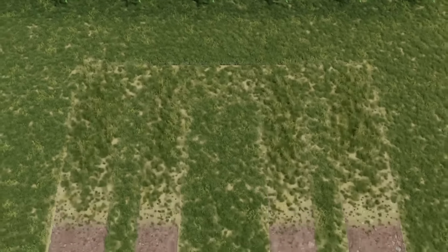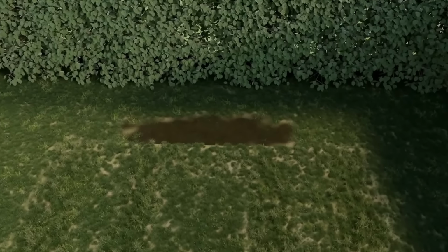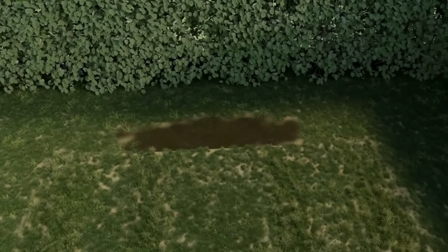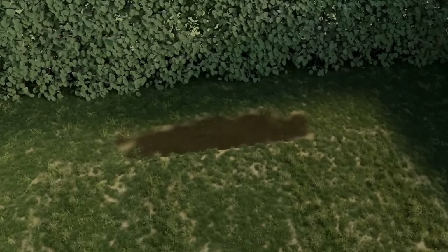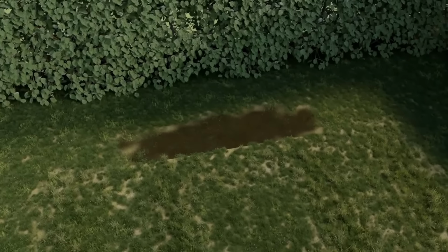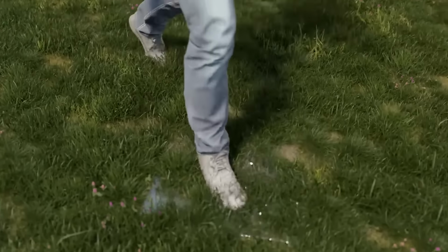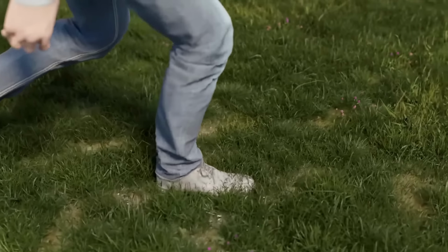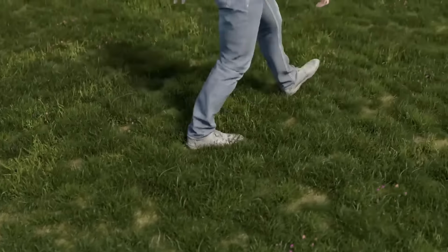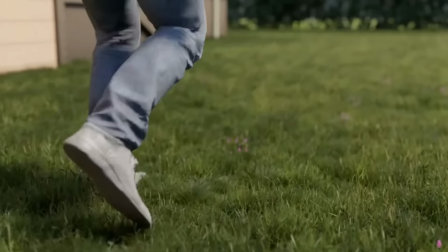If you notice taller, greener grass where your leach field is located, it is an indicator that your leach field is not functioning properly. If you notice puddles on the field, it is possible that a hydraulic overload has caused the water to rise to the surface. With a clogged leach field, the pressure is causing the water to rise. If you notice that the soil is abnormally wet where the leaching bed is located, it is also an indication that the leaching bed is no longer functioning properly.